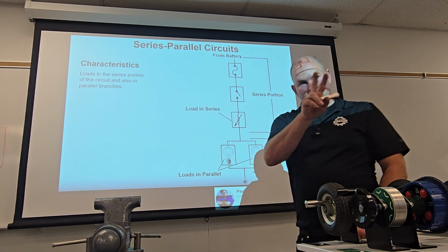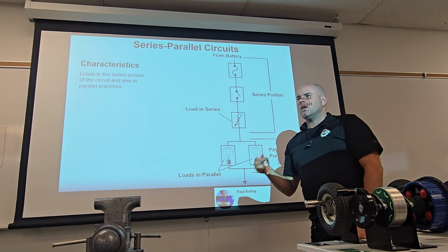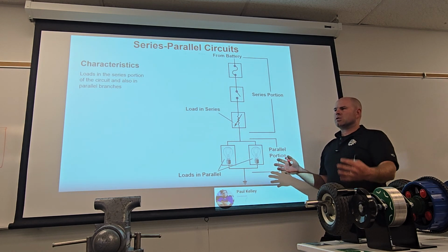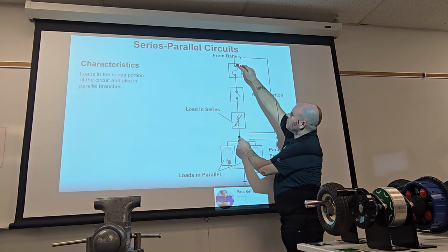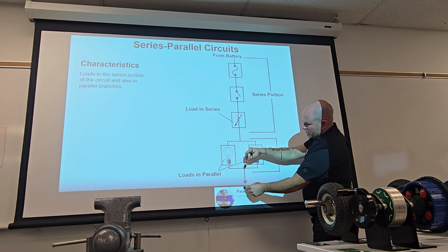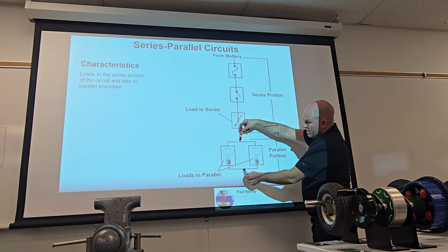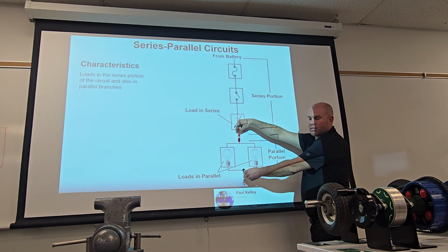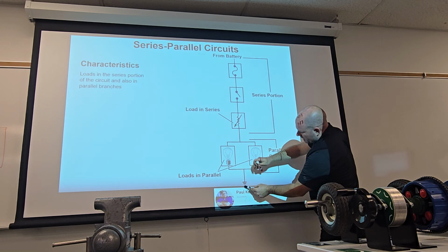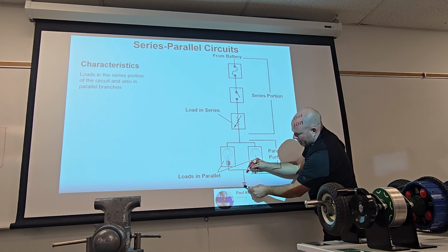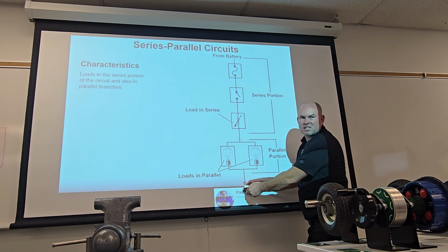I'm going to do it 2 ways for it. Because the way that the book's describing it is a voltage drop. So I'm going to do it in the voltage drop again. Right here, we should drop 0. Right here, we should drop 0. Right here, we should drop everything, 12. If we drop 0 and we drop 12, that means the problem's between the red and the black. It's a problem on the ground side. That's kind of what it's saying.